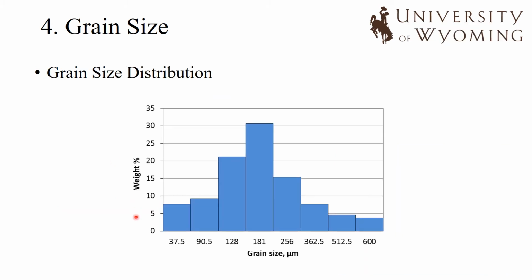And from this experiment, you can also get a grain size distribution based on the weight percent. So if you take every sieve diameter and you plot the cumulative weight percent, or you plot the weight percent that you have on this sieve, you end up having something similar to a normal distribution curve, with a certain size dominating the weight percentages of all the other sizes.